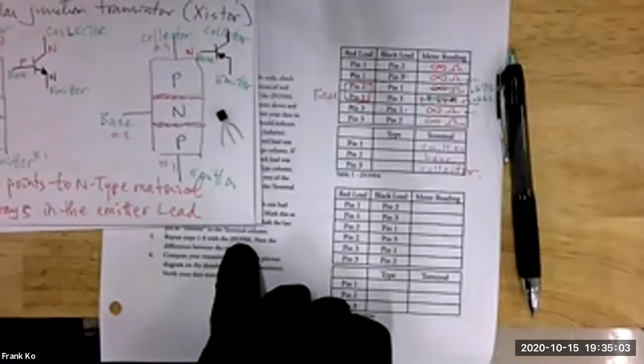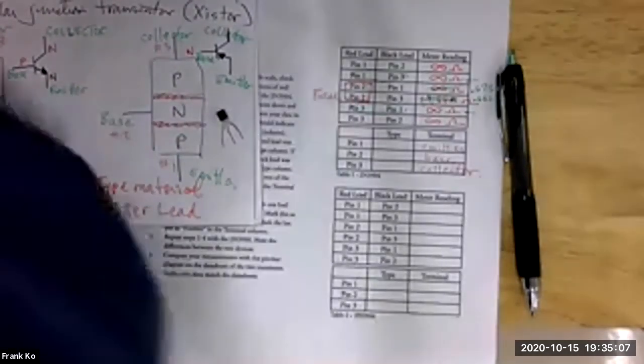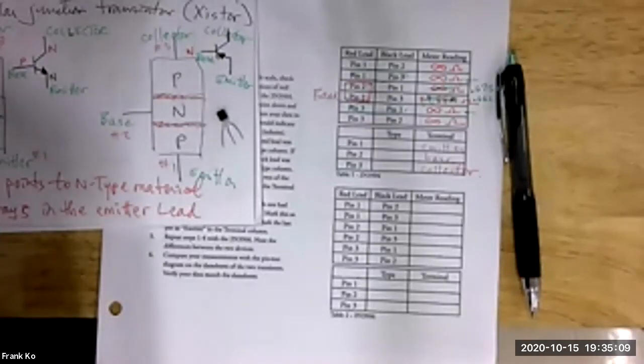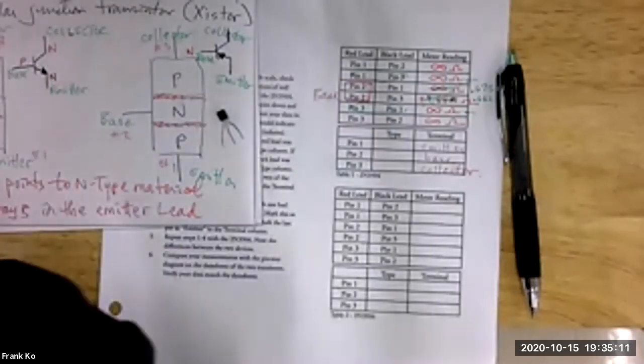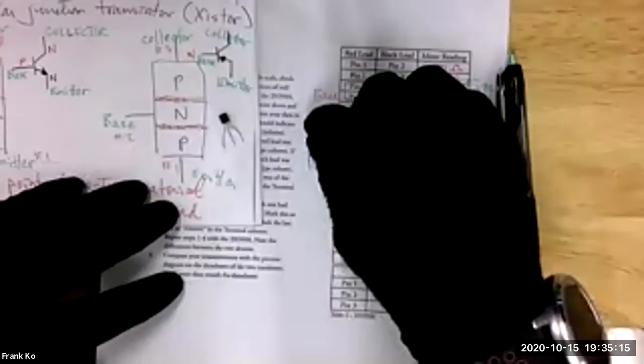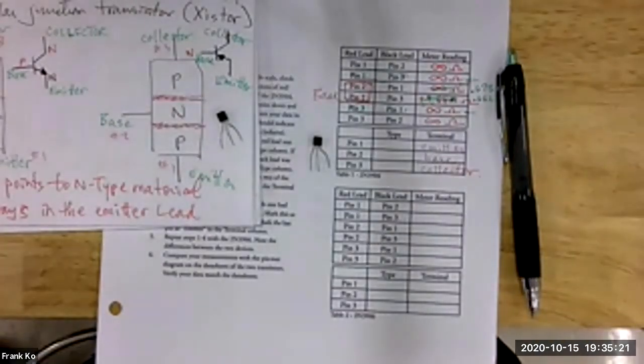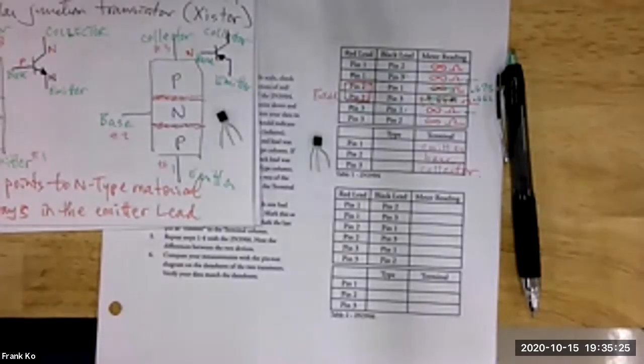All right. You have another transistor. Let's pull out a 3906. So pull out your 3906 and repeat these steps and see if you can determine if it's the same, if it's different, how is it different, what leads are which. So look at that very carefully. Hold it up to the light. You can see the markings as they reflect off the flat spot, and you will see a 3906.